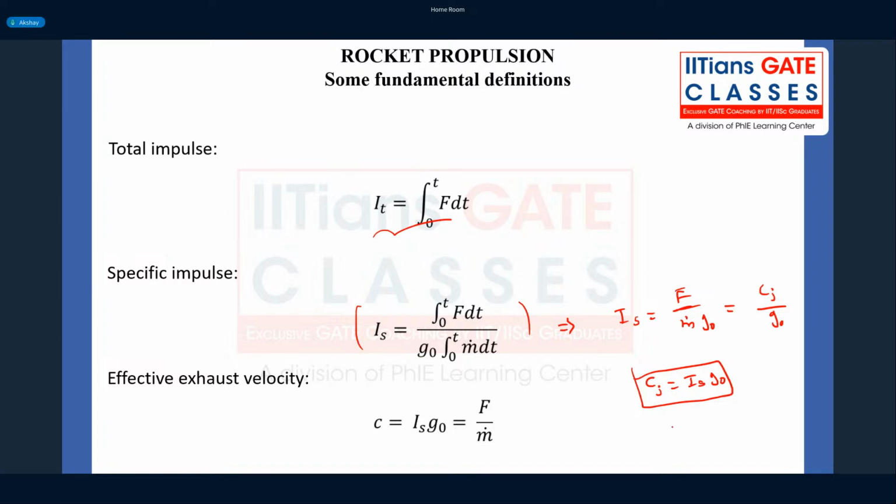Remember, there is an interesting point, right? We define effective exhaust velocity as Ve plus (Pe minus Pa) times Ae divided by the mass flow rate of the propellant. Say if the nozzle is optimally expanded, in that scenario what happens? The exit plane pressure will match the ambient conditions. So in that case this term vanishes. So our effective exhaust velocity and the exit plane velocity are the same in those conditions.